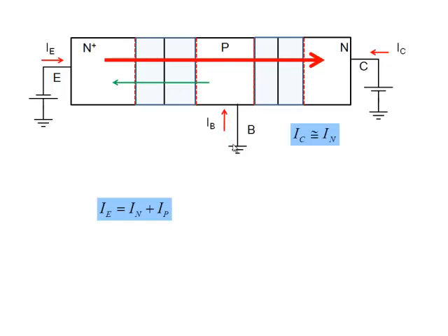The base current that goes in, what does it do? It supplies holes. And where do the holes go? The holes go here. So the base current is simply equal to IP. This is IP here, this is IN. Emitter current is the sum of these two. Collector current is simply this one. And the base current is IP.